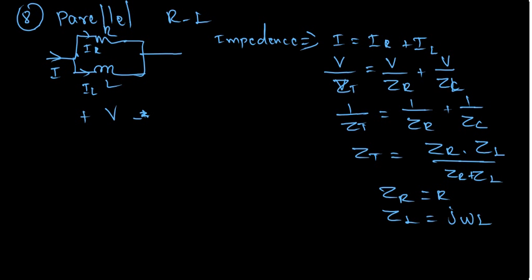And here we are going to draw the phasor diagram. It is different from the series case because it's parallel. In here, the common thing is the voltage drop. Current is not a common thing. So I'm starting with the voltage drop, and the currents IR and IL. I already told you that the current of a resistor is not leading or lagging. So the current of a resistor is always on the same line, IR.